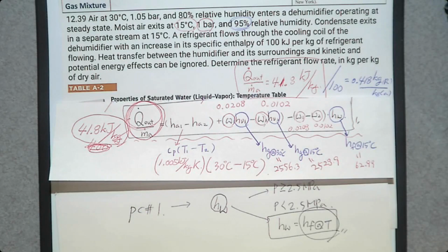That's how you analyze a dehumidifier. Oh, it doesn't matter because it's going to be multiplied by the difference in temperature. So difference in degrees Celsius and difference in Kelvin, they are the same because you are going to add 273, add 273, they're going to be canceled. So the specific heat capacity unit is Kelvin, the temperature is interchangeable. You can use Kelvin or degrees Celsius. They're both okay.